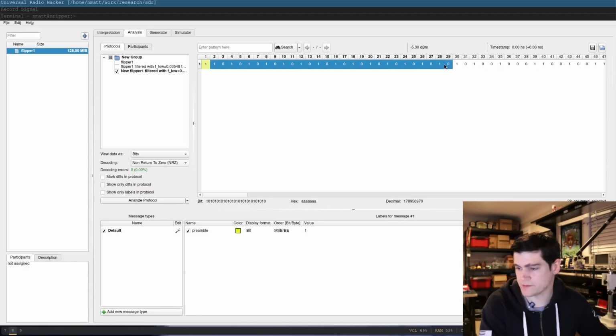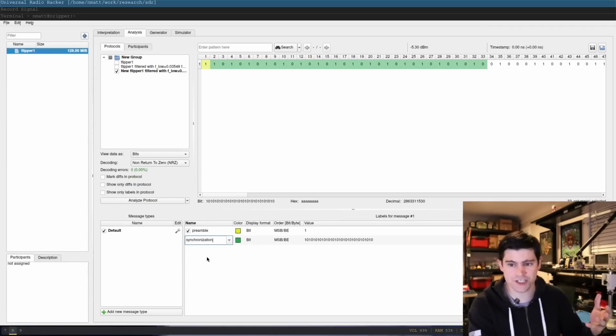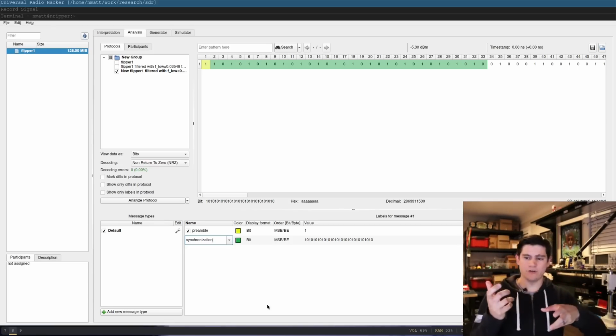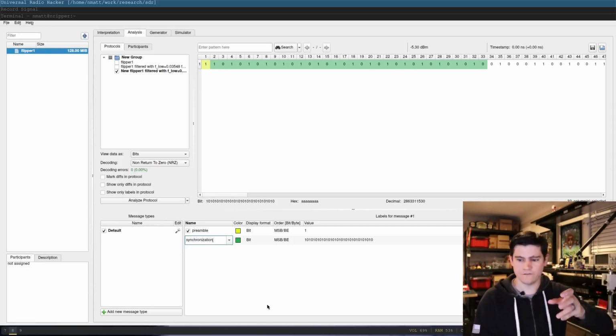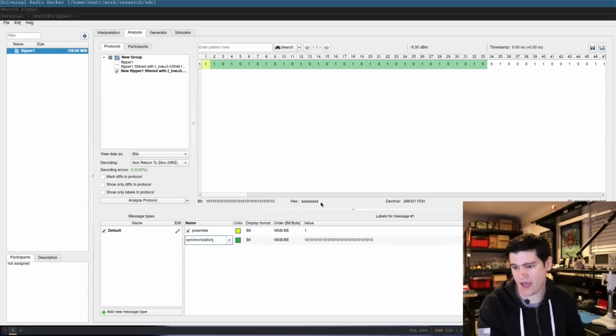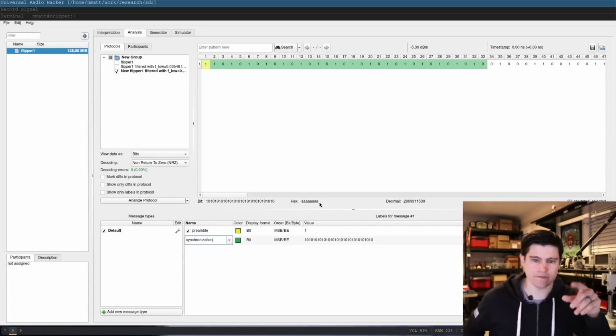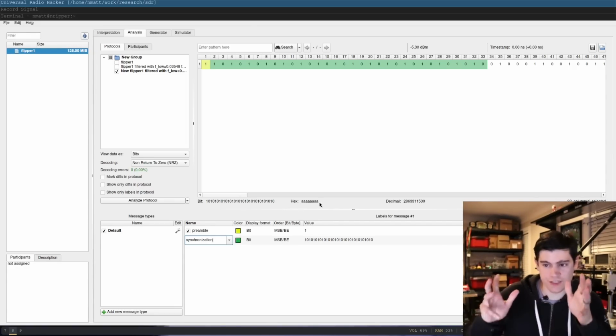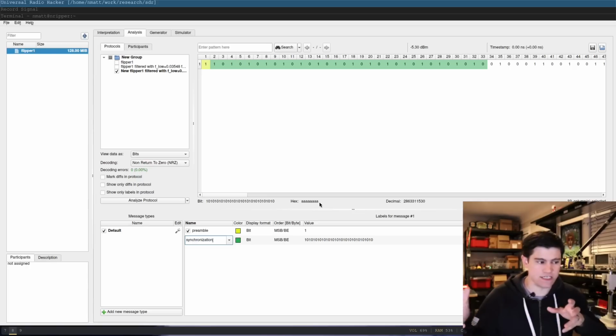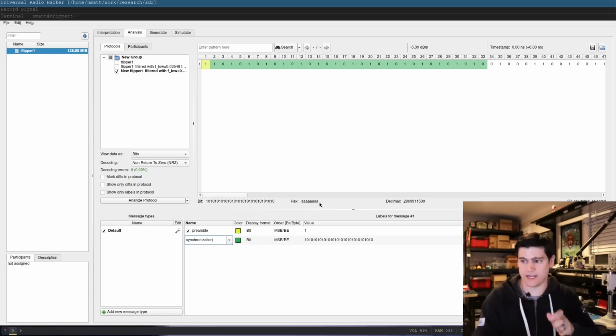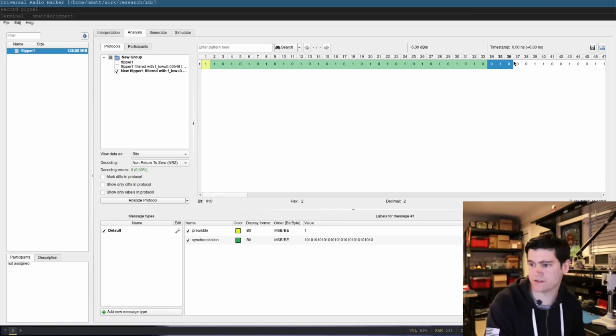It's just 1 0 1 0 1 0 1 0. To there, and then I'm going to create another label. It calls it synchronization, so a radio receiver could just listen for that hex value, a 8 times. Once it sees that, that's how it knows to synchronize and start the message directly after that.